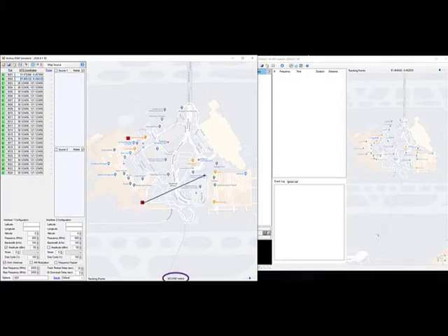And then we'll go on, measure. You can see on the bottom again the meter position, how many meters distance the next probe is. Place your probe. And we'll place one more probe arbitrarily in this location. You can add more probes if you like, or use a minimum of 3 probes in order to do the simulation.